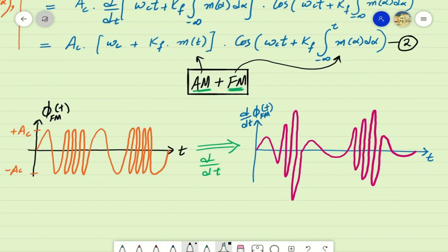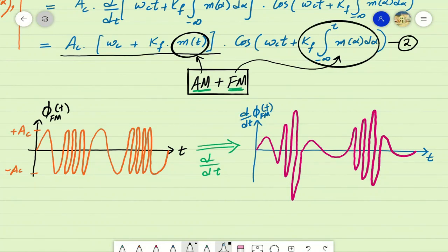So for the intervals where there was a low frequency observed, after taking the derivative, we will have a low peak amplitude of this derivated signal. As evident in this equation, the peak amplitudes are directly proportional to the information signal, as well as the phases are being modified with respect to the integral of the information signal. So information being directly added in the frequencies here and information being directly added in the peak amplitude here is directly influencing both the frequency and amplitude of this signal.